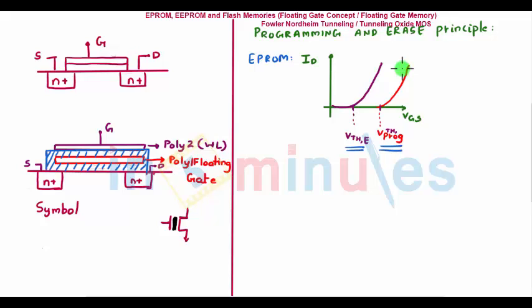We'll understand how you can get a threshold voltage of such a high value and what we are trying to do. Basically, if this is my NMOS transistor, which is a normal transistor, when VGS is greater than VTN, we know that the transistor is turned on. I want to make this threshold voltage so high that when I apply a VDD also at the gate, my transistor will still not turn on because the threshold voltage is higher than VDD. In doing so, we'll be able to program our EEPROM. Let's see what and how. But the thing we understood from this part is that we need to increase our threshold voltage, and EEPROM revolves around storing charge on the floating gate. Keep these 2 points in mind and we are set.